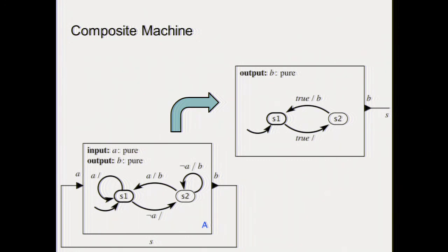So we had a finite state machine to begin with. We had the feedback loop, and we encapsulated that feedback loop and tried to find the machine that has the same behavior as the original machine plus the feedback. And this is it. The way in which you compute is exactly the same as we did before. You assume something, you propagate, see what happens. You assume the opposite, and you see what happens. So the method to compute what that finite state machine ought to be is always going through analysis of what happens to the various values of input.